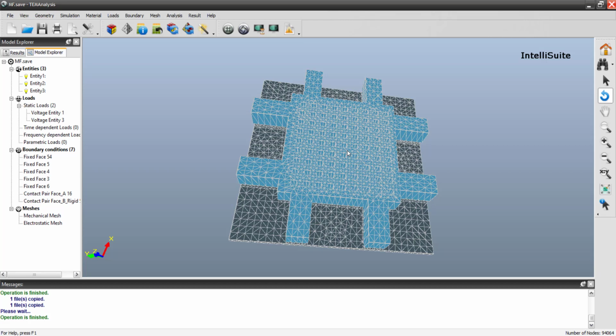So here we are looking at pressure, the acoustic pressure. This is a microphone. When we are looking at acoustic pressure as an input, if there is a displacement due to voltage, then it's a wrong signal. But we require voltage to be applied for measuring the capacitance. So we need to find a safe zone of voltage where we can get the capacitance as well, and the electrostatic force of attraction is very minimal.